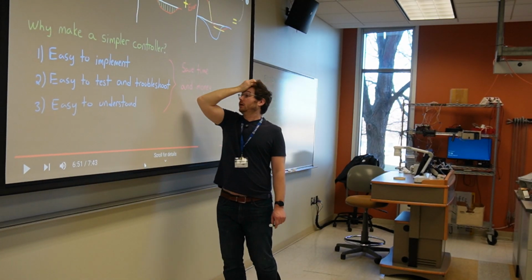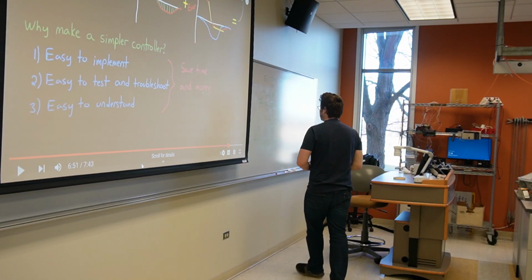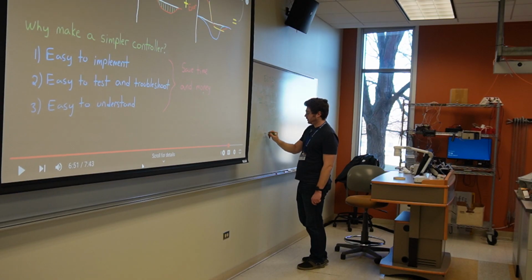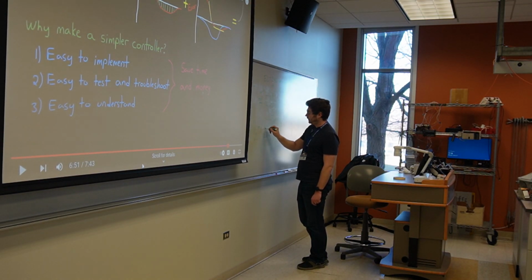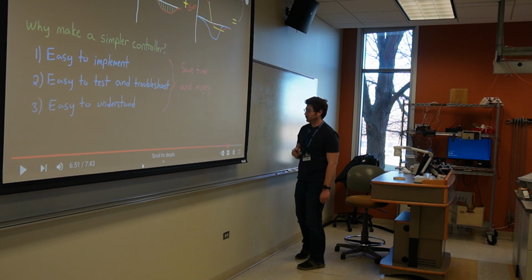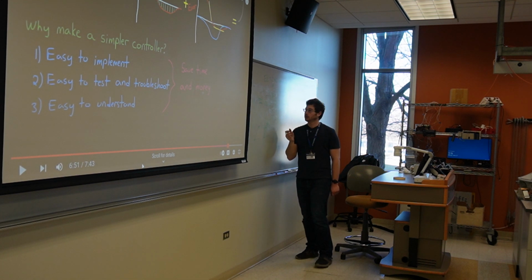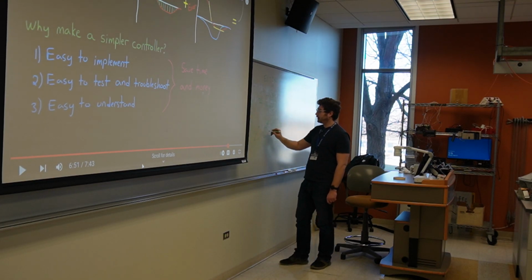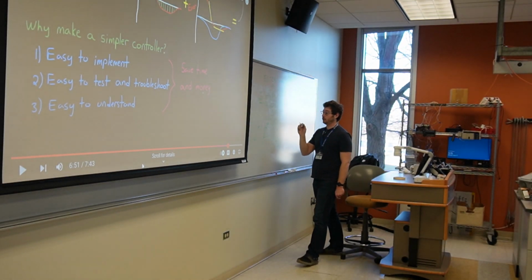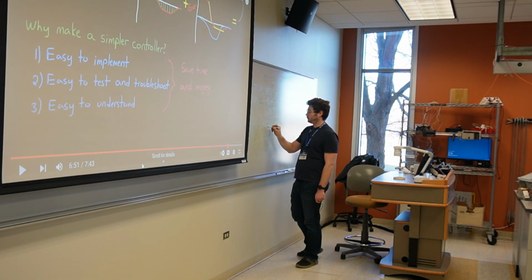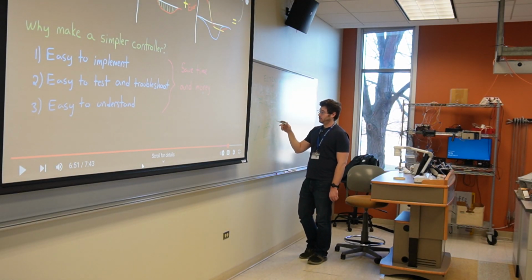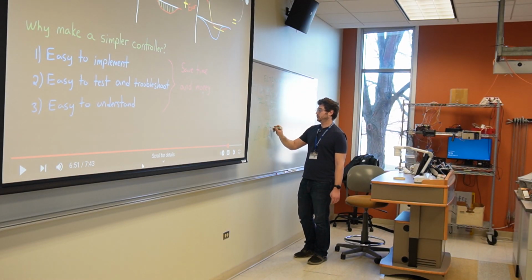Okay, so for the output of each of these controllers, for example, if our proportional controller says we're here on our tilt table, but we should be here, it says you need to push this hard. That might be like 30% of our motor power. The integral controller would also add on top of that. It says, we've had this amount of error for 5 seconds. I really want to correct that. I'm saying we should add 50% motor power. The D term might be set to 0, so it's like, I don't really care, 0% power.